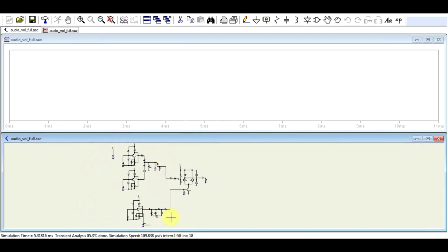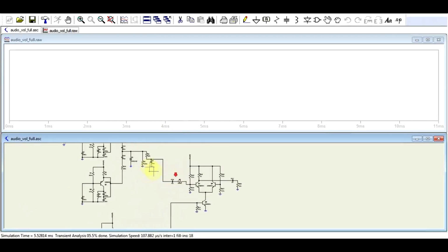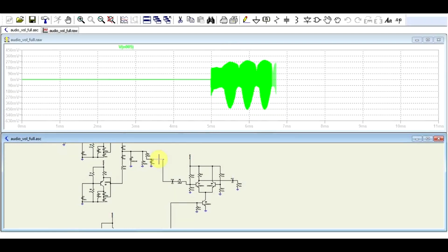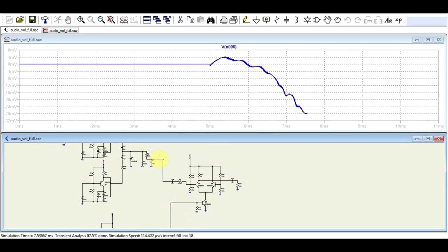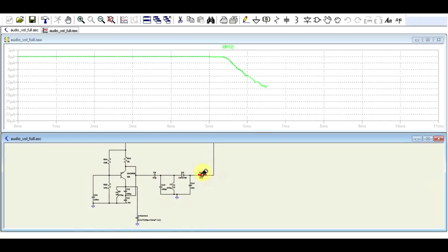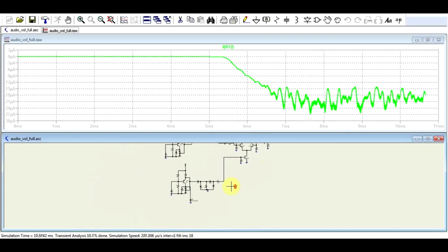Being such a huge circuitry, it's working extremely slowly. We can see how the 2 signals coming from the 2 oscillators combine. So this is the heterodyning in action. Then when we look at the detected signal, we can barely see anything. If we look on the volume control side, we can see that there is some current coming through this. Again, it's not perfectly straight, it's not perfectly filtered. This circuit still needs a bit of work, so the circuit is not finished, but it's operational.